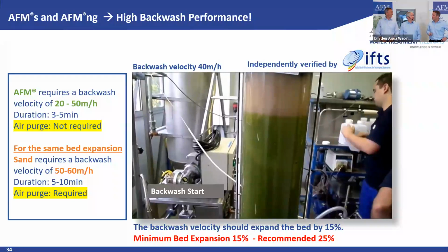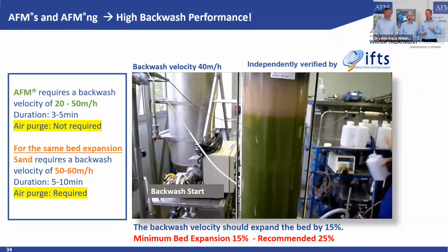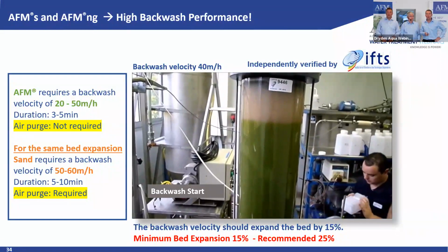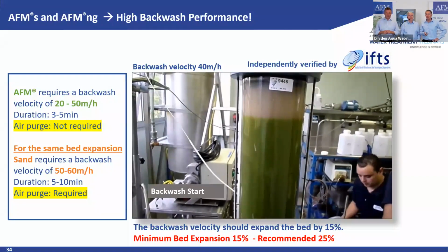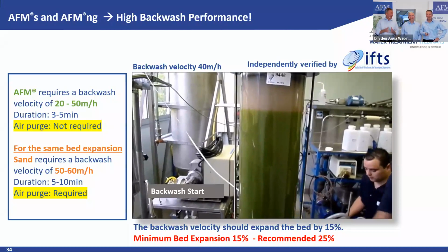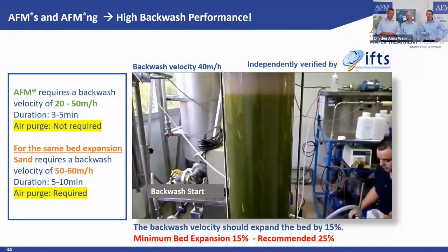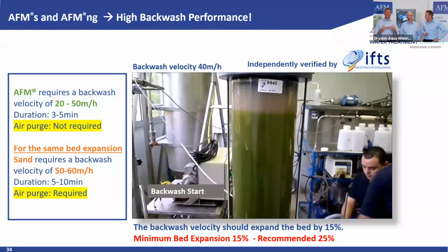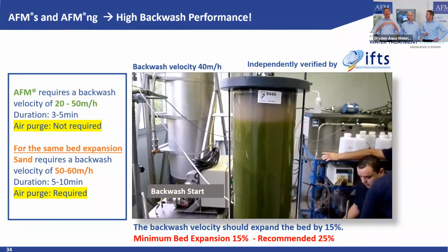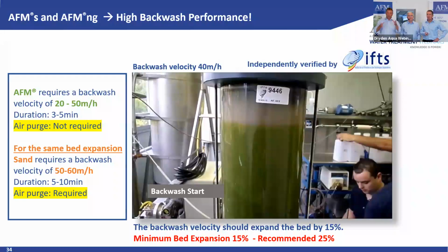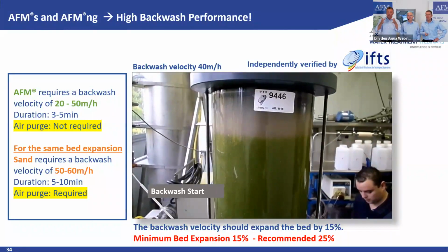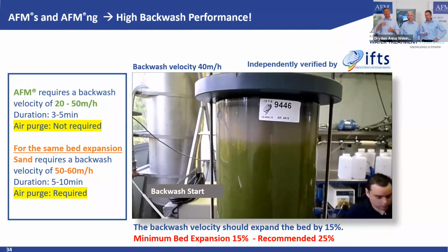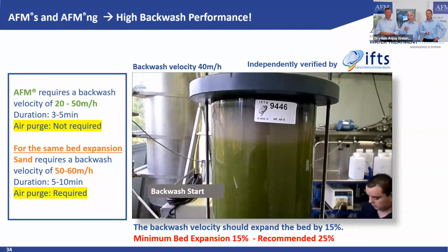Also, when it comes to backwash, a fast and short backwash is better than a slow and long backwash. Now, gentlemen, this is not in all cases of your life the case, but here in backwash, short and fast is the right solution. And why is this? Because you want to bring the particles to the top of the filter bed, but you really want to wash them out. So you need these drag forces to bring, especially if you have heavy particles such as heavy metals, to the top of the filter bed and to remove it. Yeah, exactly.